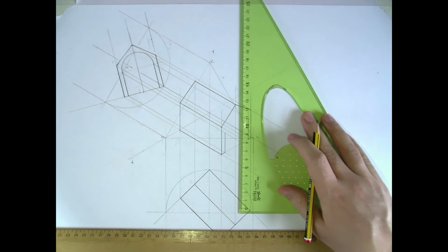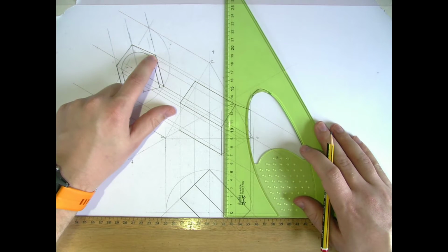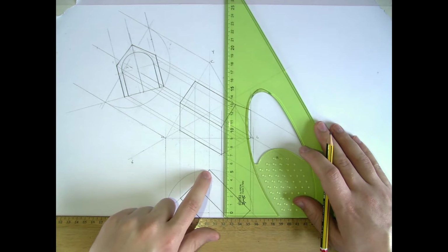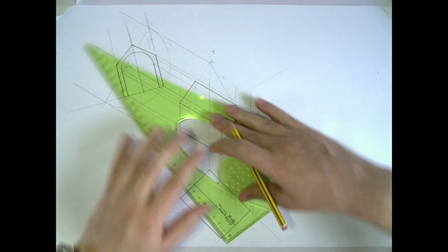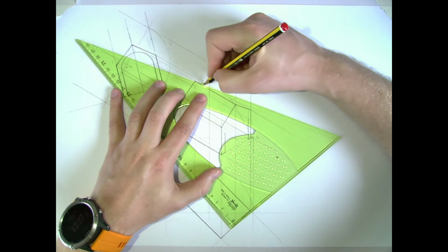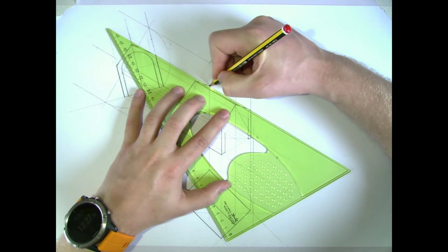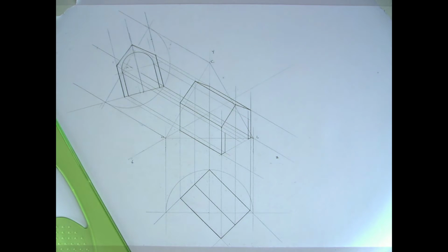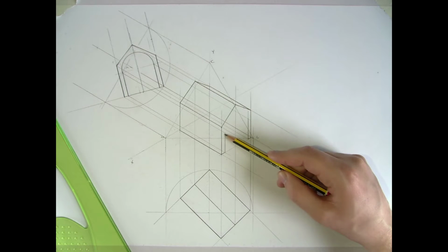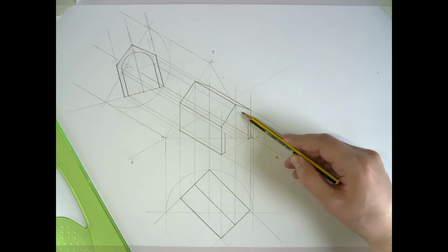And now we have the back corner. So the back corner is at this height, so it's following that one down. This is that corner in plan, and that line is projected up here. That completes the sides and roof of the kennel. So the only piece now that needs to be done is to draw the axonometric projections of the front of the kennel to include the semicircular opening. So we've already started that, we've got 2 lines on it, now we just need to put the curve part onto this also.